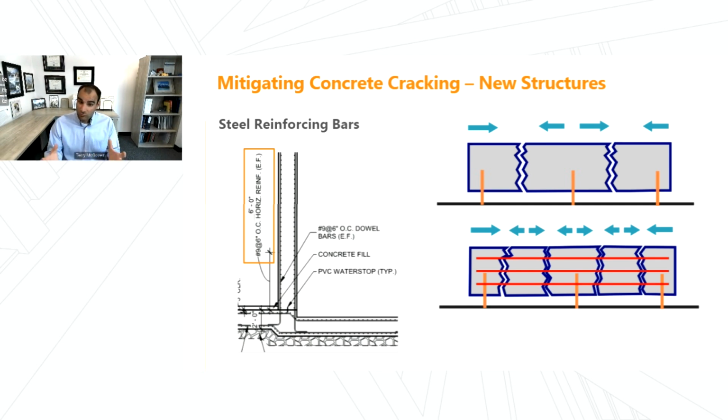We're saying if we have ideally no reinforcing, right, idealistic situation, we may get 2 big cracks. Well, if we add a reasonable amount of reinforcing, maybe we can produce 4 cracks and have all those cracks be tighter so that we don't have that potential for leakage through those cracks.